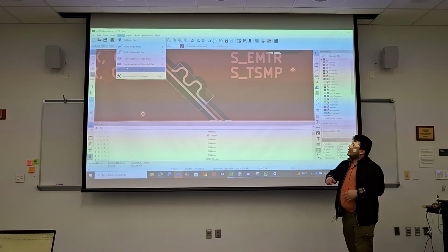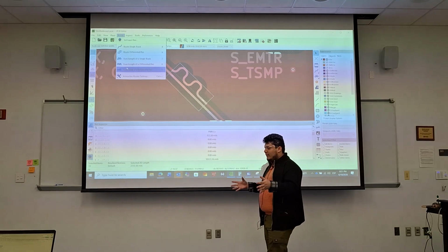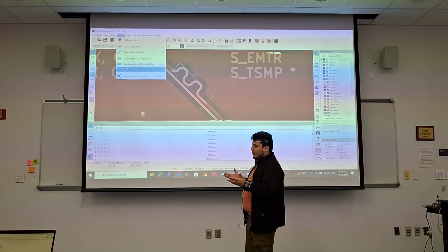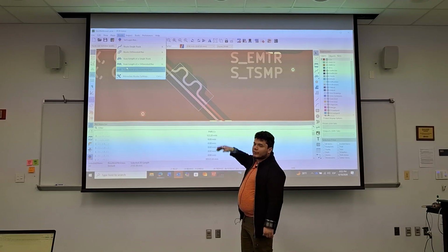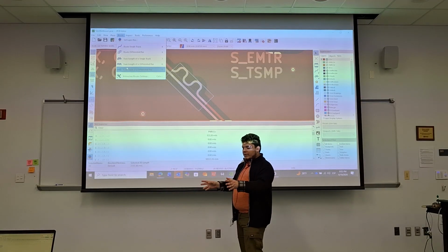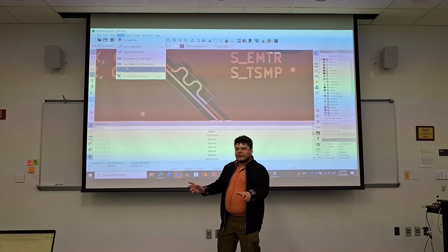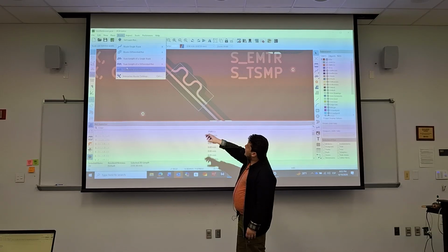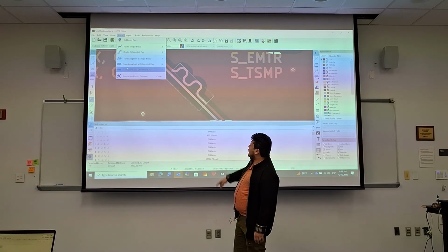Sometimes you can also do other serpentine tuning if you need different nets to be the same timing. So for example, if you need your MISO and MOSI, for whatever reason, to be tuned to the same length, they're not a differential pair, but you would have to tune a single track, right? Or if you had two differential pairs that have to be the same distance between the pairs, then that's when you would tune the length of the whole differential pair. But for just one half, you would tune the skew.